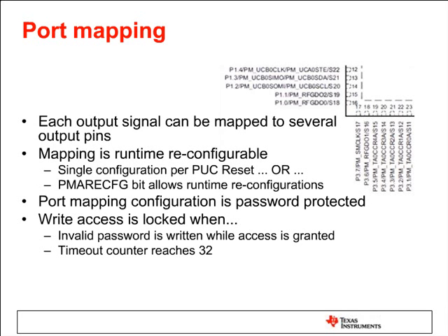So here, for example, I have my serial communication, my serial clock, slave in, master out, slave out, master in, or my GDO signals from the radio, or my timer signals. And I can map any of these signals to any of the port mapped ports. There's 3 port mappable ports, and I can take one timer PWM and output it to 8 signals on that port, or I can mix it up in application if I so choose.